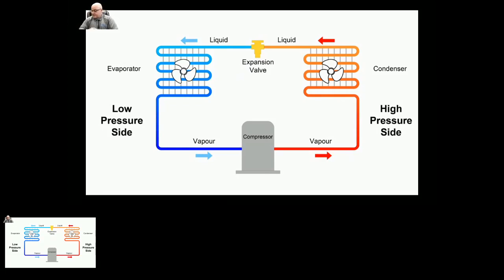So to recap, we have the condenser to reject heat, we have the evaporator to absorb heat, we have the compressor to change the state of the refrigerant from low pressure, low temperature to high pressure, high temperature, and then the liquid coming from the condenser is metered through a metering device. This is everything that we need to know. Obviously, there are more details to this, and of course, there is always more information to share about this.